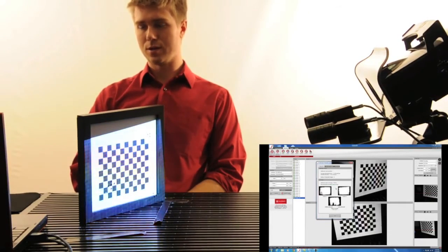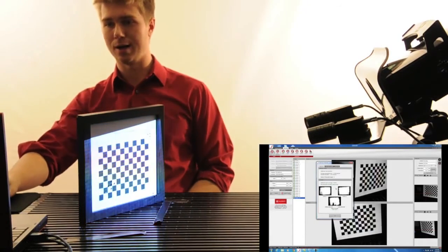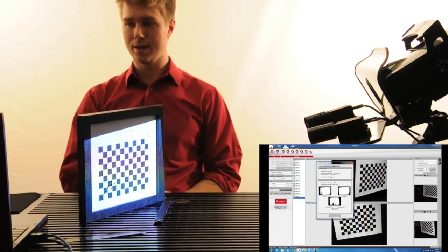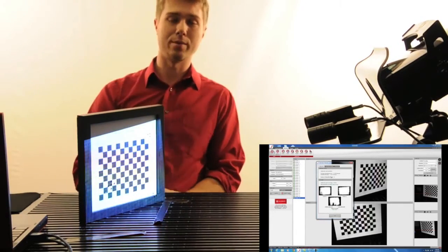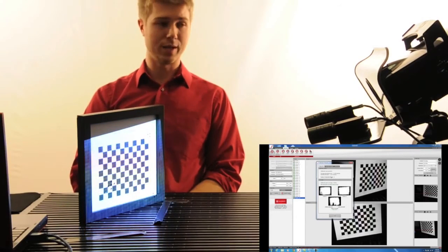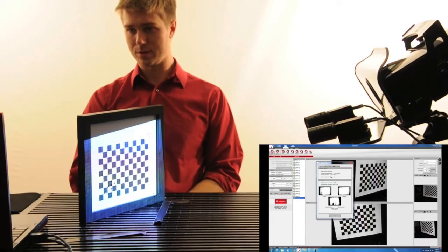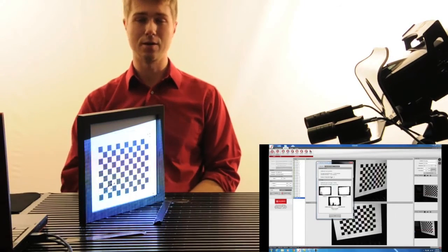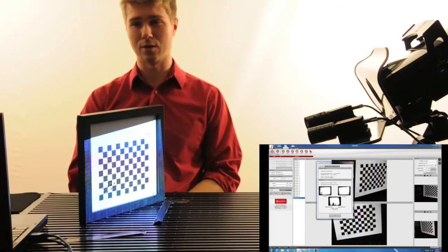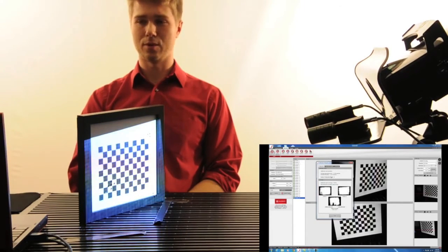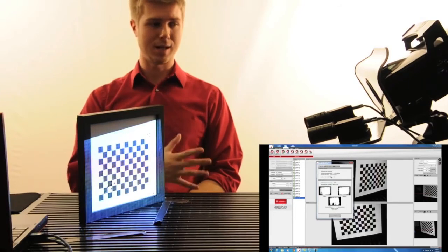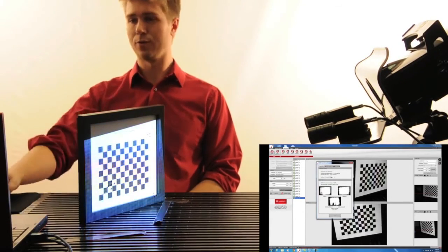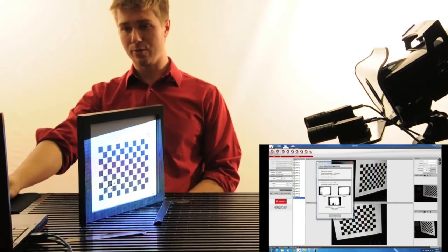Then we will also want to keep an eye on our standard deviation. So our standard deviation for this setup is plus or minus 19.3 microns. Now, if you're using a smaller setup, that number is going to be smaller, and if you use a larger setup, it's going to be larger. It depends entirely upon what size lenses you're using, where they are in position to the camera, and so forth. So once we've done that, we can begin scanning.